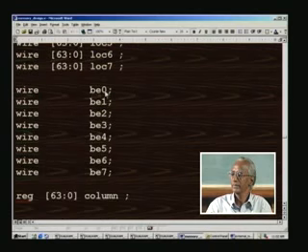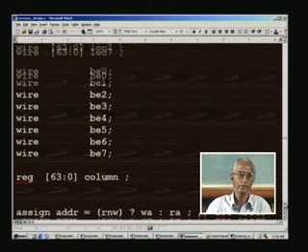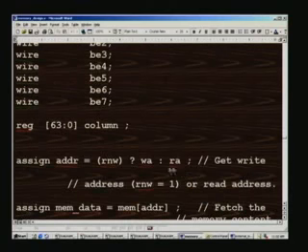Then we also have signals derived from B7 through 0 we have seen earlier, that is different, and from this one, this is local, and there is more to this here, and they are all using assign statements, therefore they are declared as wire. And we also want to access column wise, we want to read column. So what we do is we have to have another signal for column, and that should be 64 bits, and that is in an always block, therefore it is declared as reg.